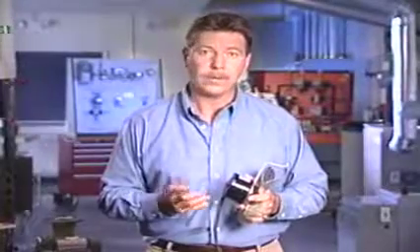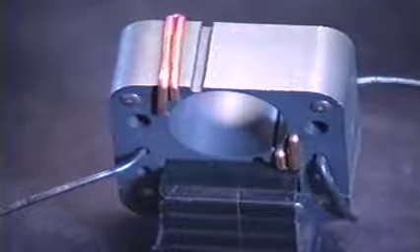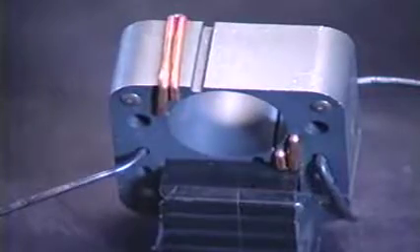The shaded pole motor is intended for use when the application does not require large amounts of starting or running torque. These motors are commonly used to operate small fans that are connected directly to the motor shaft. In order for the motor to start turning, starting torque, or a twisting force, is required. In the shaded pole motor, this starting torque is provided by heavy copper bands that are wrapped around a portion of the stator winding. When the motor is energized, a magnetic field is produced by both the shaded poles and the main winding. These fields are out of phase with each other, causing the twisting force that is needed to start the motor.